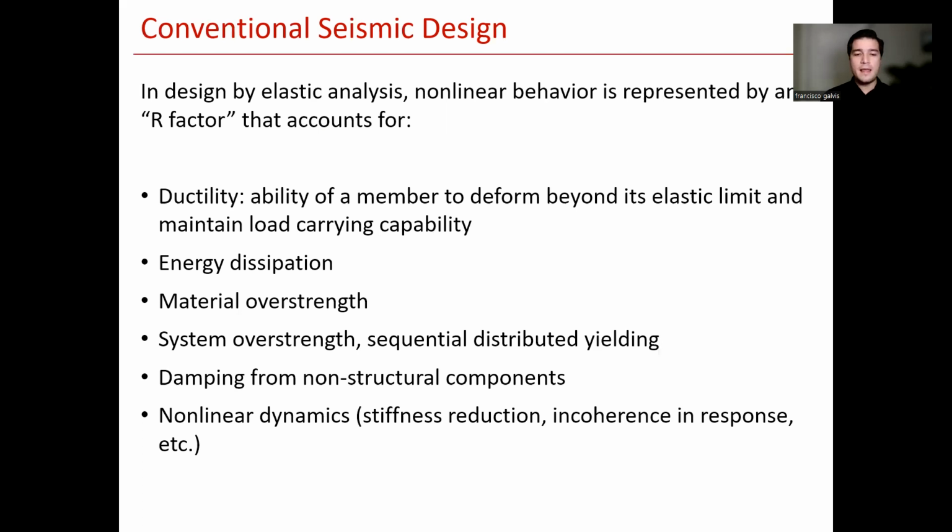And the concept, at least what the building codes predicate, is that they want a cost-effective structure, right? A structure that would be safe enough for a fair amount of initial investment, right? Because we have the tools to make buildings just withstand any earthquake elastically, right? And barely suffer any damage. The trouble is that they will require a lot of material, a lot of steel, concrete, really huge elements that would cost a lot of money and would place limitations architecturally and all that.